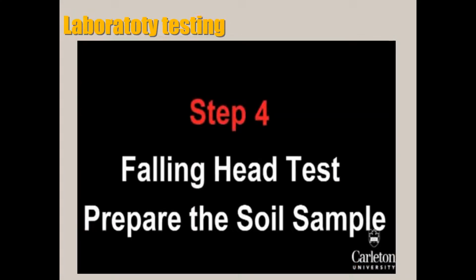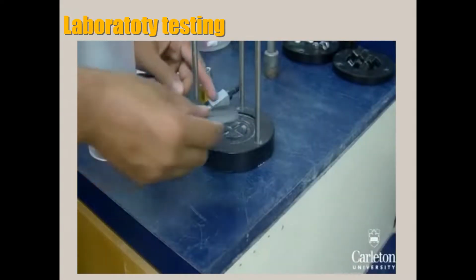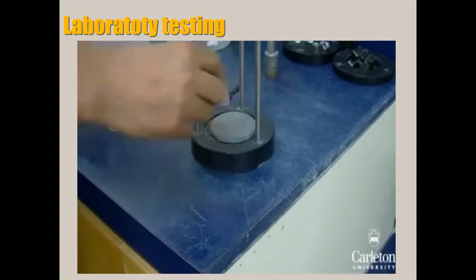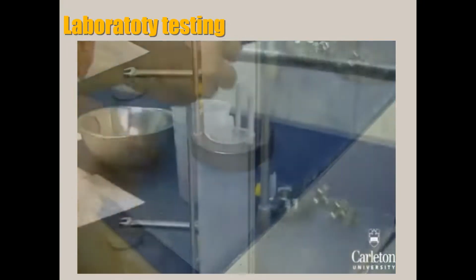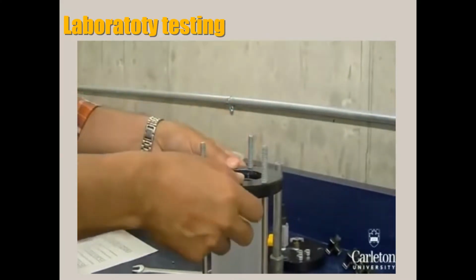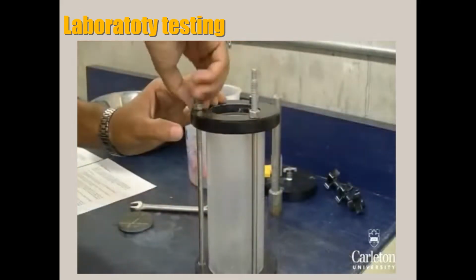For the falling head test, first we need to put together the test cylinder. Unlike with the constant head test, which uses a screen, the falling head test uses a porous stone. Place the porous stone on the base like this. Now place the tube which acts as the cylinder's walls over top of it. Then thread the end cap with a hole in it onto the 3 protruding screws. Secure it with 3 nuts. This is to create a tight seal.